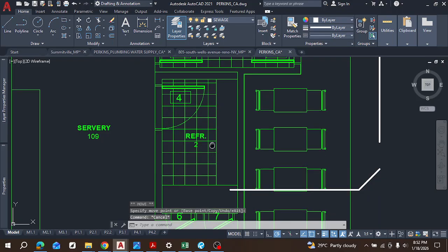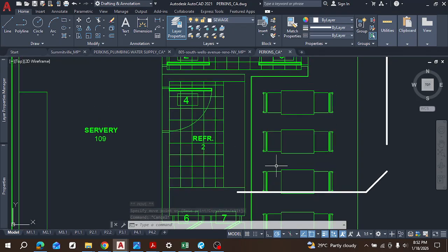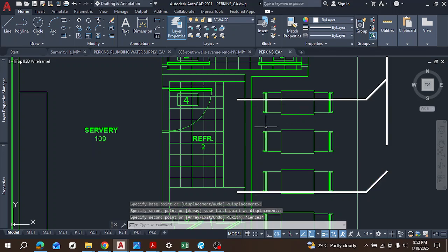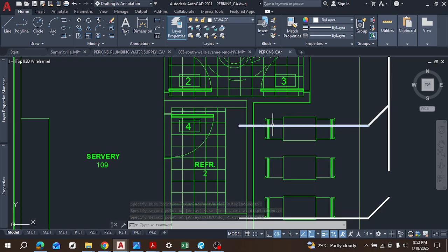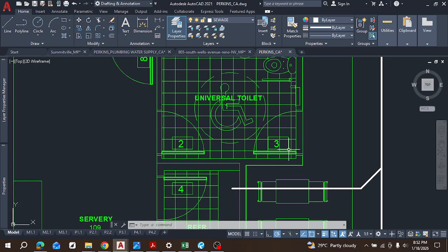Okay, so that I can capture this, it will cover maybe this half of the system, and then we can also just copy this because I need something similar up there. Right, so you move it somewhere here, this other half, just to cover it. Now our floor drain releases water into this system, and the floor drains will also have their own traps too, because within this pipe there are likely to be bad gases that we don't want to enter our building, so there will be traps.